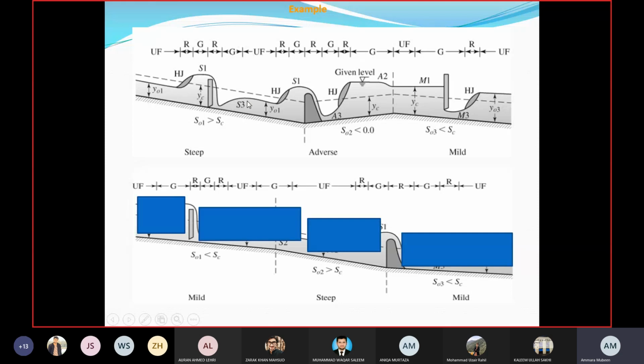So for supercritical flow, the upstream control section governs. Okay, so this S3 is made, and then again the uniform flow depth would be between the two control sections, and then again how to sketch that, you have to think similarly.